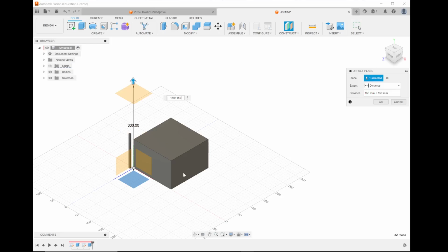You can put simple equations in Fusion, and it will do that. Where this is usually used for is not so much addition, but let's say if you had a tower that was 275, and you wanted to put something in the midpoint, you can just divide that by 2, and then you know what that length is. Or you can divide it by 3, and you can know what that length is. That's what the equation thing is pretty good for.